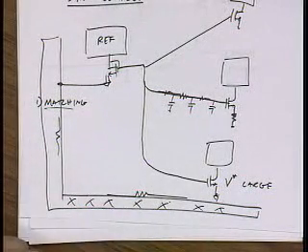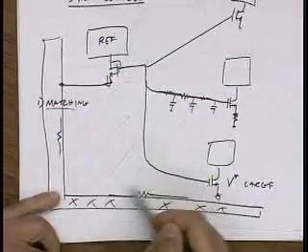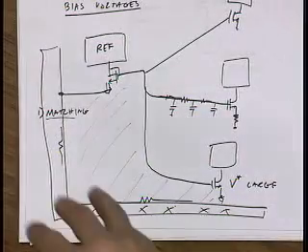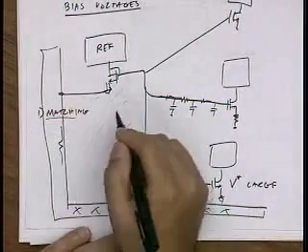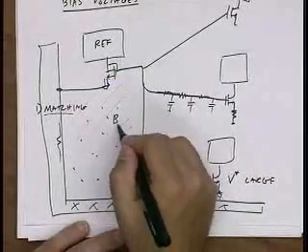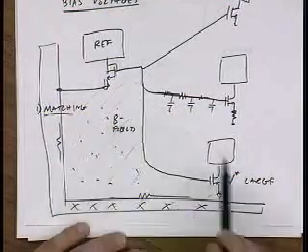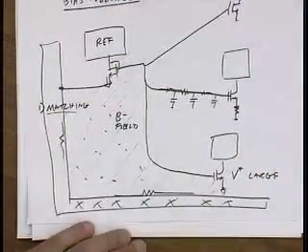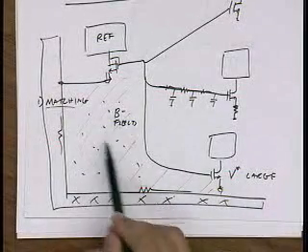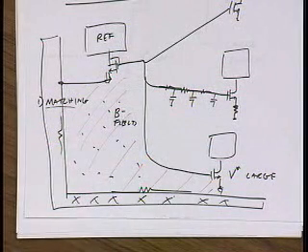But now you've introduced a huge loop, right? And so if there's any kind of magnetic fields, let's say coming in perpendicular, so these are B fields, then that introduces a voltage around this loop, which causes basically your bias current to vary with the frequency of the B field variation. Okay? Where does this magnetic field typically come from?